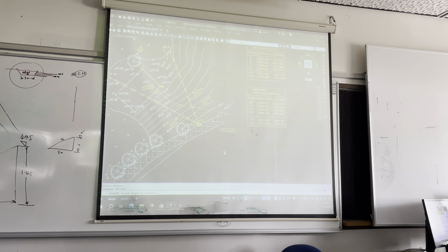Now what could go wrong here is that you have drawn your road starting from the left and coming back to the right. So you do need to make sure that when this goes on there, it starts doing it every 5 metres from the right. I've drawn mine the right way around. You may have to redraw it or redo the order when you go P-edit and you pick the things, go from right to left.